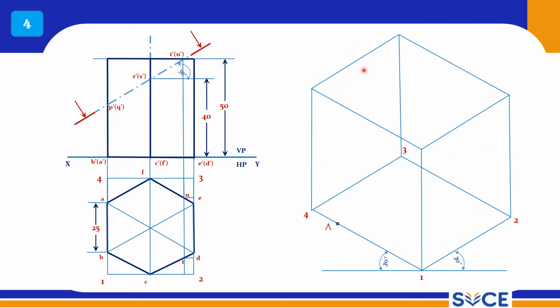So this is the box for this prism. Now this is the box method. This truncated prism I am going to enclose within this box, keeping it in three-dimensional view within this box. So this is my point A, and I will get point B here. I will get point C, the center point. If you project it, you will get point D, and if you project it, point E, and this is F. So base points I have obtained. From A to the top rectangle you can project, and this is again A, B, C, D, E, F. I will get all the points on the top surface.